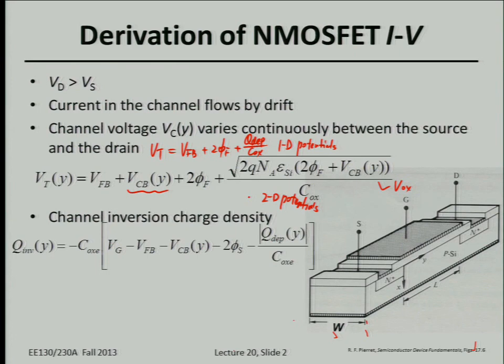Also, once we induce some charge on the gate to balance the inversion charge as well as depletion charge, the inversion charge and depletion charge tend to trade off, right? Once you increase the depletion charge for a fixed gate bias, for example closer to the drain side, simultaneously you reduce the inversion charge concentration. For the source side, because you have the least depletion charge, at a certain fixed gate bias you're expecting to see the maximum concentration of inversion charge.